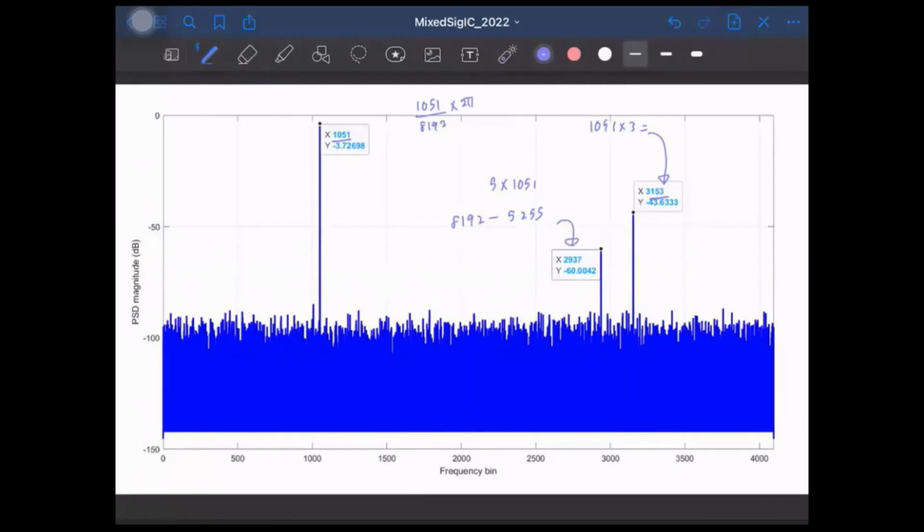Okay. So if you don't know this, you might think that this is slightly weird because, you know, we expect from our intuition that the strength of higher harmonics should be lower and lower. So we expect that we should get something like this, right? The strength should keep reducing. But here you see that this bin, that is this frequency, has a lower strength, and the higher frequency here seems to have a higher strength. Okay, and this is happening because our higher frequency component, that is the fifth harmonic, has aliased back and fallen back to this frequency. Okay.